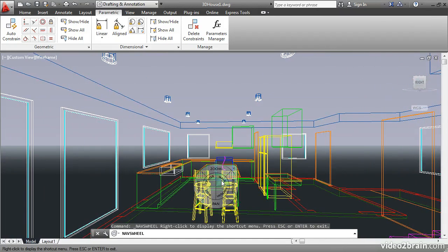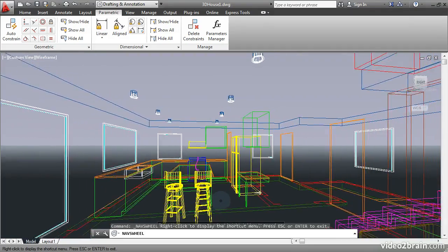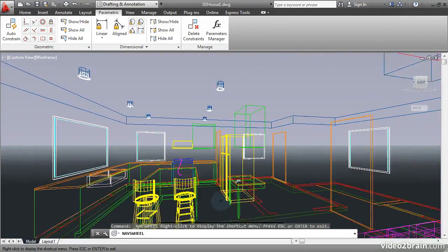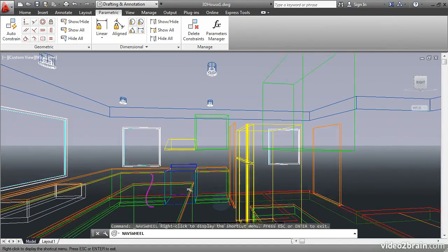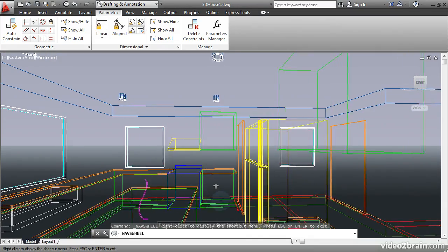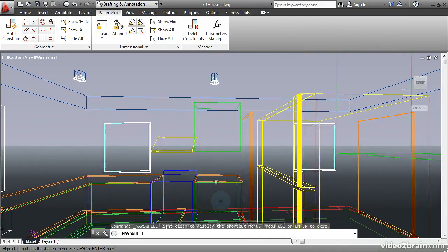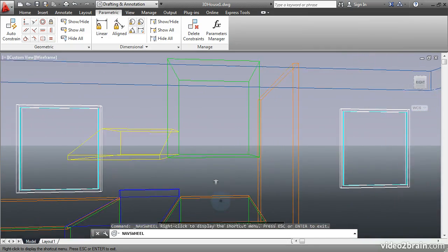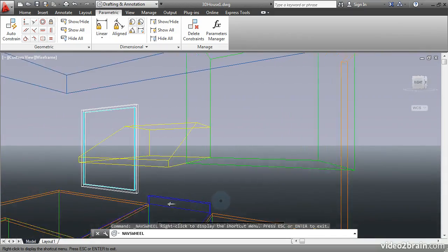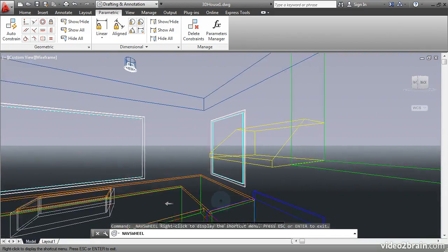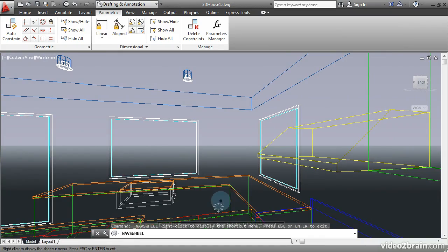Try that again. Click and hold on walk on the steering wheel, and then drag the cursor to the right to rotate right. Drag it up to walk forward. Drag it left to rotate left. See if you can walk in this area between the kitchen island and the refrigerator. When you come up here to the stove area, drag to the left. You can also back up by dragging down.